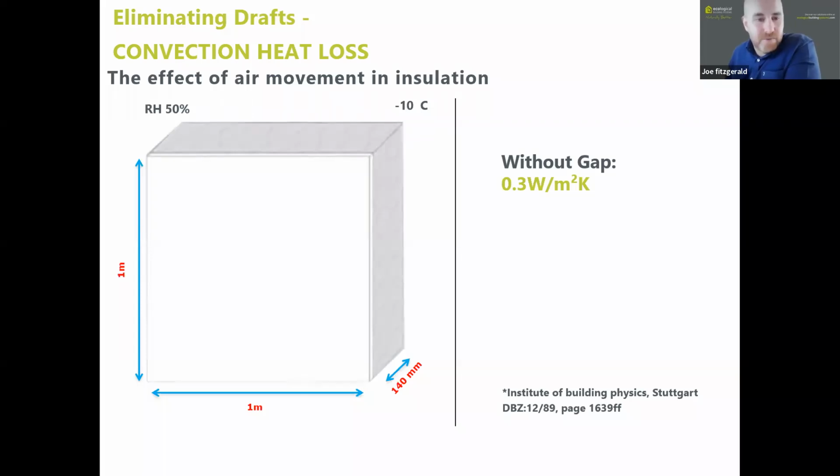So my software assumes these perfect conditions, but in the real world, there's sockets and things, and there's gaps in the fabric, and there's badly sealed connections at windows and stuff like that. So to illustrate some of that, they just cut the membrane 1 millimeter for 1 linear meter. And now they retested it, knowing full well that convection was possible.